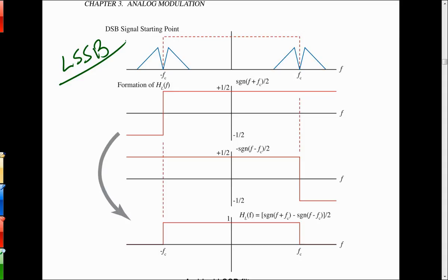So your instinct based on what you know from electronics and signals and systems is, I'll just build a low-pass filter that cuts off at FC or does something along those lines, and I'll get the lower sideband that way. And that could work too. But the mathematics of the Hilbert transforms allow you to get a very precise relationship here, and that's what we're going after right now, to show analytically how you can write down exactly what the single sideband signal will be.